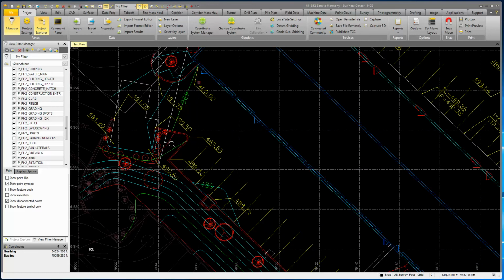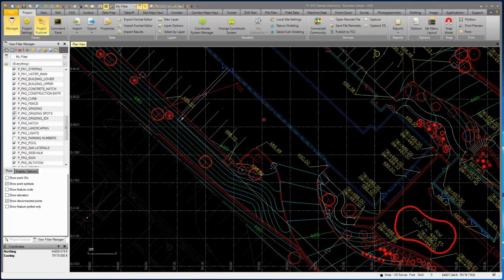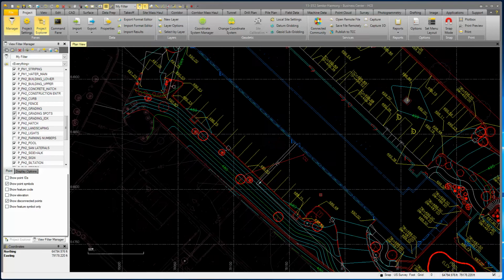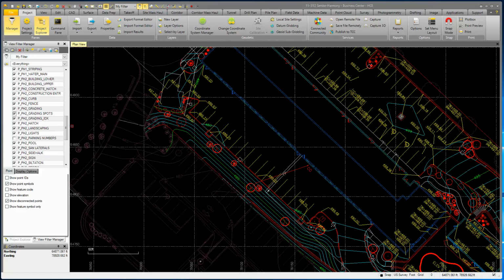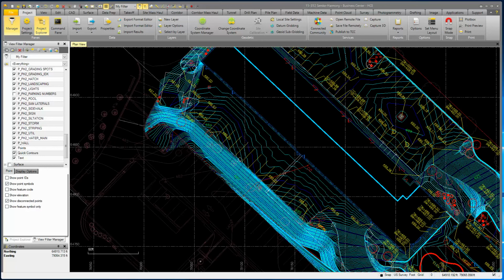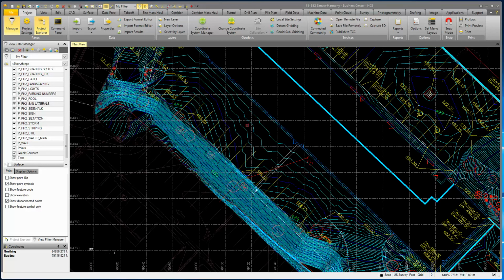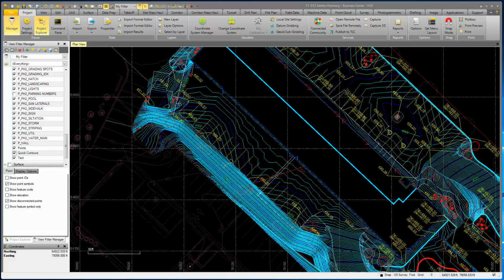Here's a curb that comes around. Here's elevation 490. And if I come across this parking lot, there's another 490. And it should sheet flow from a straight line grade down to this next row, where you can see the contours are kind of sloped where we get some nice grading. So if I turn on my quick contours, you can see the contours, and these are at a tenth, so we get a little bit of variation in here, but that's typically what you see when you contour out at a tenth. But if you see, we have a straight line grade across here, and we have some settings where this is nice, smooth, and it follows the contours.